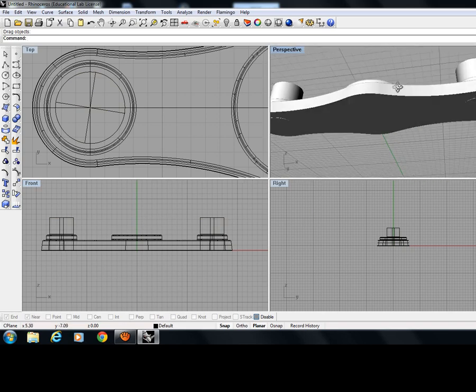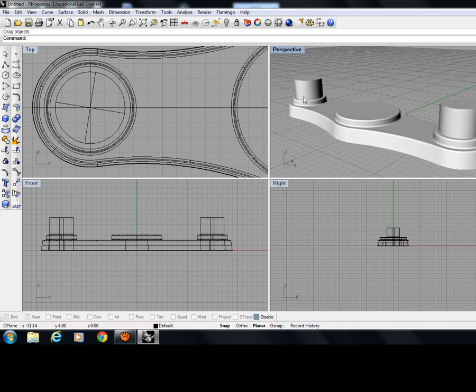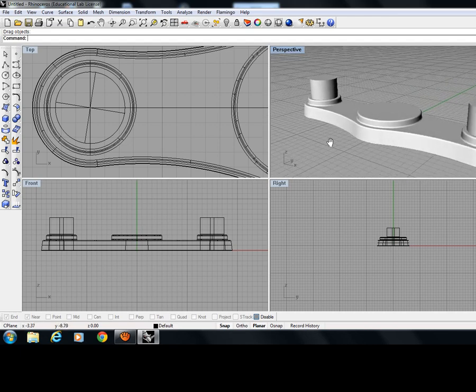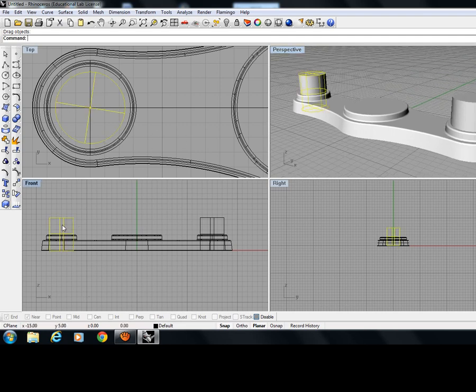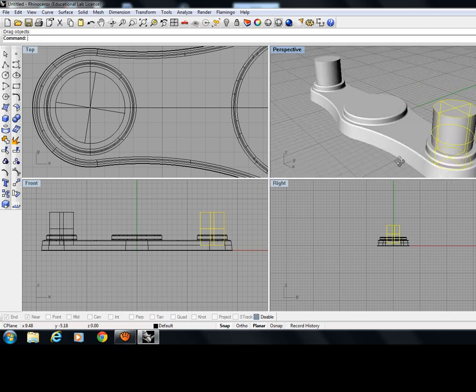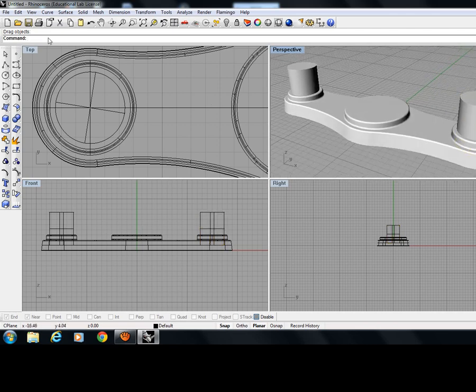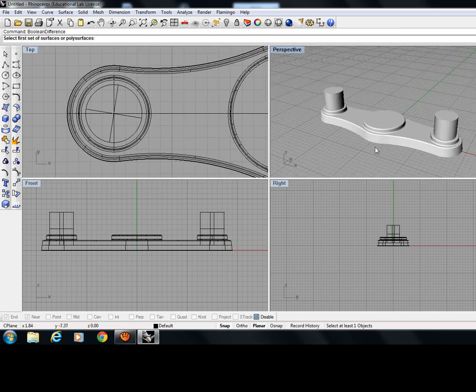Now what I want to do is that I want to take this out so I can have a hole inside where it's going to be my faucets. Okay, now let's just place them 1 centimeter up, okay, so they don't show on the bottom part. See, on the bottom part it doesn't show. And let's use the following command, Boolean, but this time is Boolean Difference. What we're going to do is that we're going to take out part of a solid. Okay, so Boolean Union and Boolean Difference are very important tools.